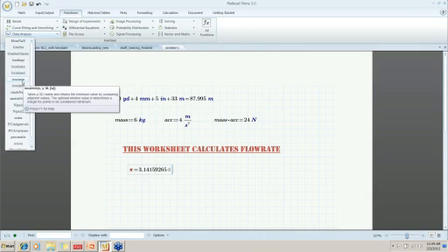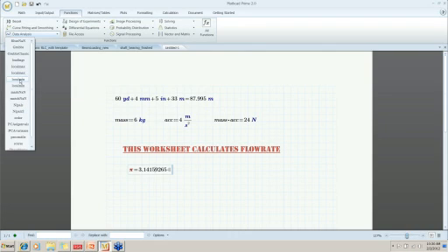Okay, local min takes a 3D matrix and returns the minimum. And you can see what the arguments are that are required to call that function. And if you click on F1, we have context-sensitive help. So click on F1, and the help page for this particular function, local min, will pop up. So you don't have to go to the help menu, put in a search term, and go through that process. You can just click on F1 here, and automatically the help will come up for that function.